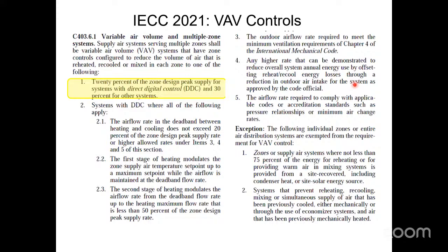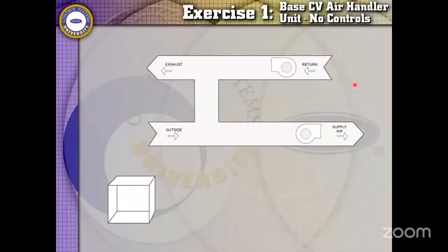So you modulate it more and more and more closed, then you can energize the heater. And if the heater needs more CFM to stay online, you can start modulating it more and more open. For the most part, you don't have to think about this because every DDC manufacturer already knows this. It's been in the rules for a while. So they already do it this way. If you had an old system, then you're under the old code, so who cares? So new systems, it pretty much is happening on its own.